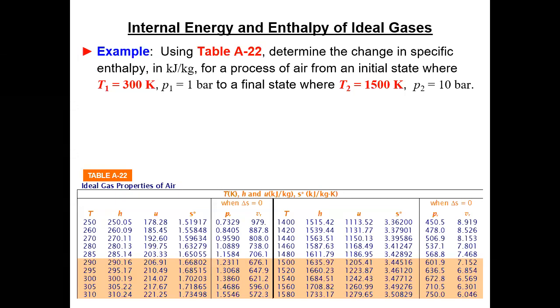Well, first of all, if we're assuming ideal gas behavior for an enthalpy change, do we give a hoot about the pressures? We don't. We're throwing away any variation in enthalpy with pressure, so those numbers don't come into play. If you're plugging into an ideal gas model, PV equals mRT, that makes a difference because it's your variable. But if you're just evaluating an enthalpy difference, assuming ideal gas behavior, that's just extra information put in there to confuse you.